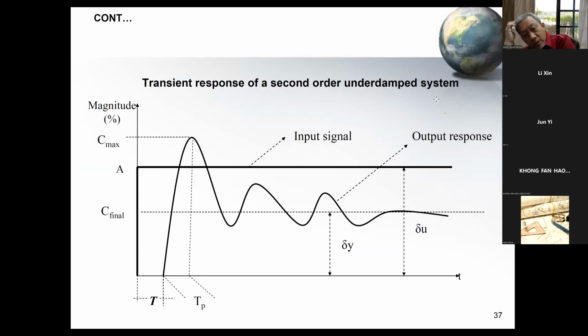When we take the data from the experiment and plot it to verify, it gives the same shape of response. Of course we have a time delay, and this is a typical second order system with values of zeta and omega n, plus some error at the final value.